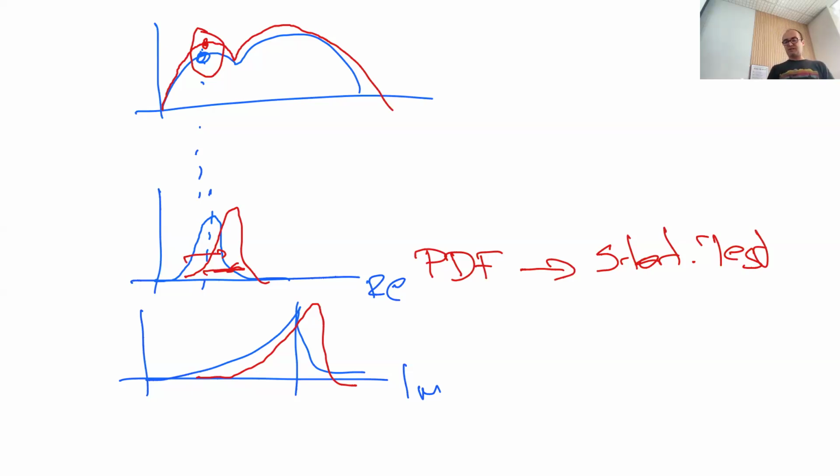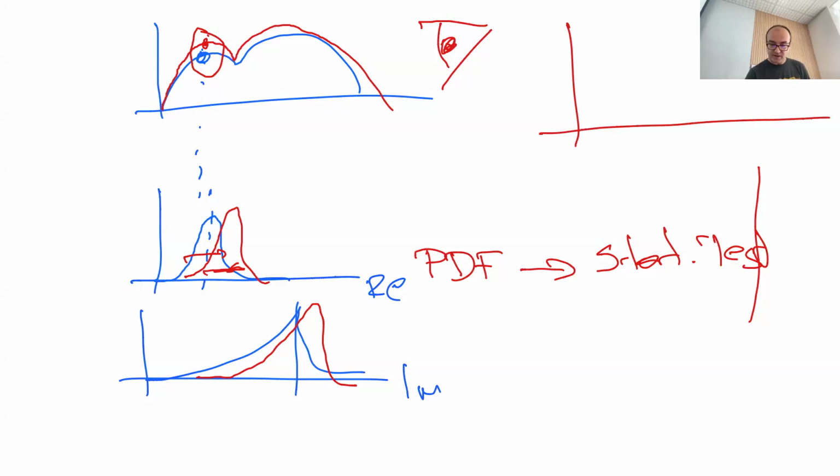And because we can do this, we don't have to ever look at our EIS curves with our own eyes. We can use simple statistical tests to check whether some changes occur. And because we know the frequencies of all these points, we can always draw stuff like this. We have a reference.